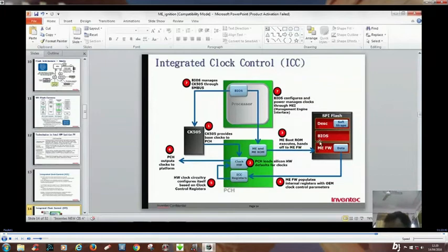But if the AMI firmware is getting corrupted, then this corrupt data will go to the ICC register. Corrupt data will configure the hardware clock, and a wrong clock will go to the platform, and that means the board will restart after some time. Usually it will restart after 30 minutes. So if you find any kind of i3 i5 boards getting restarted after every 30 minutes, the first thing that you have to keep in mind is, if AMI firmware is present, that means you have to edit the AMI region of the BIOS chip, right? You have to edit the AMI region of the BIOS chip.